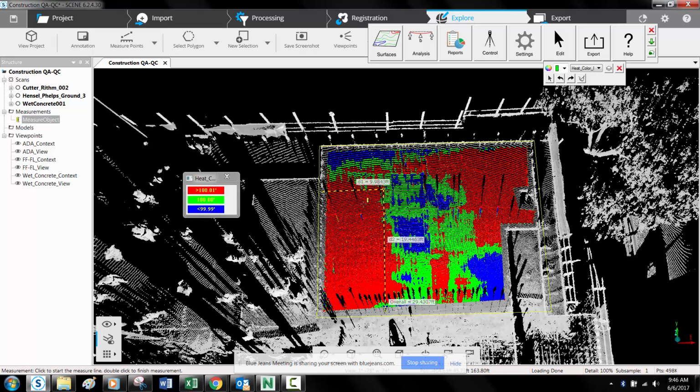But now to get to Stephen's point about height adjusting the point clouds. So if the target is 100 feet, it's important that the point cloud is at the correct elevation. And we all know that the barometer inside of our scanners is about as accurate as the GPS. So it's going to be anywhere from, say, 5 to 10 feet. I would not want to trust the elevation of the scans that come in fresh.